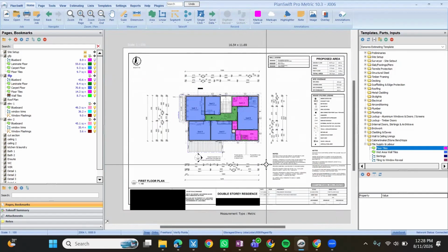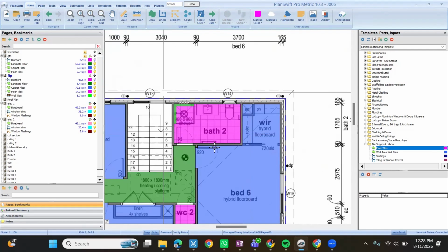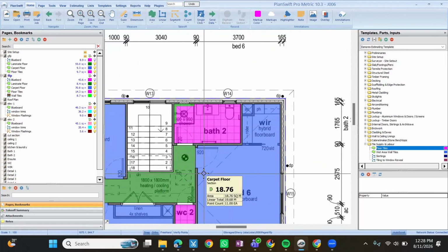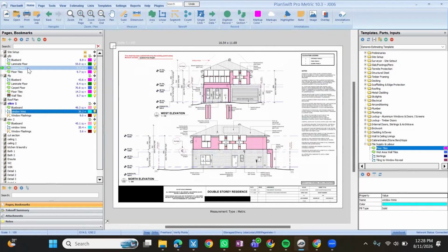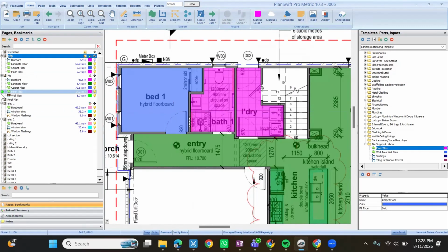Again, guys, application of wall tiles depends on the client and on the builder. Most of the projects that I handle, they usually put wall tiles only on shower areas. But in some cases, they allow wall tiles for the whole wet area. And for the height of the wall tiles, usually it's around 2.1 or 2.2 meters, but sometimes clients or builders suggest until the ceiling area. Let's see here. Yes, there's also...